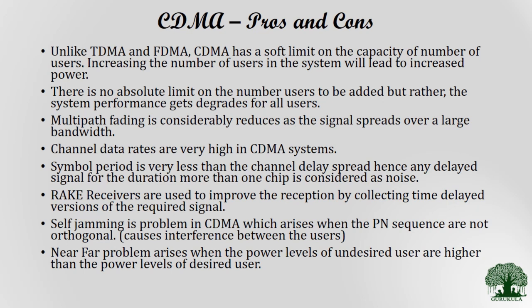And the symbol period is very much less than the channel delay spread. Hence any delayed signal for a duration of more than one chip is considered as noise. So any signal that is spread over a particular region, we consider that as noise.